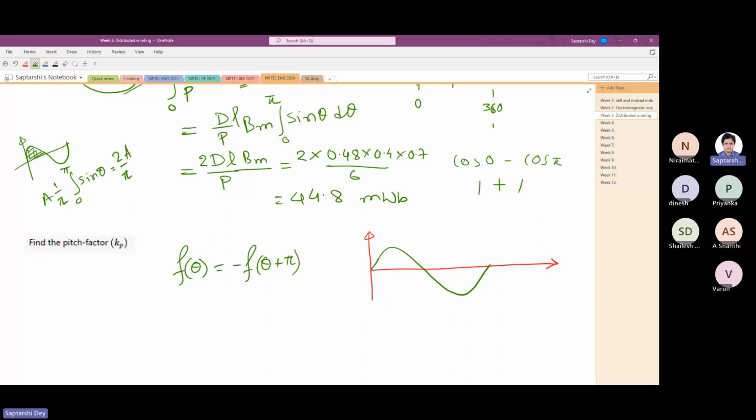Okay, so if you have a coil here at some theta, and you have the other side of the coil at theta plus pi, that is under the other pole but at similar magnetic flux density distribution. So whatever EMF this coil end sees, E, similar EMF this coil end should also see, E. And what you get at the coil is E plus E, that is 2E.